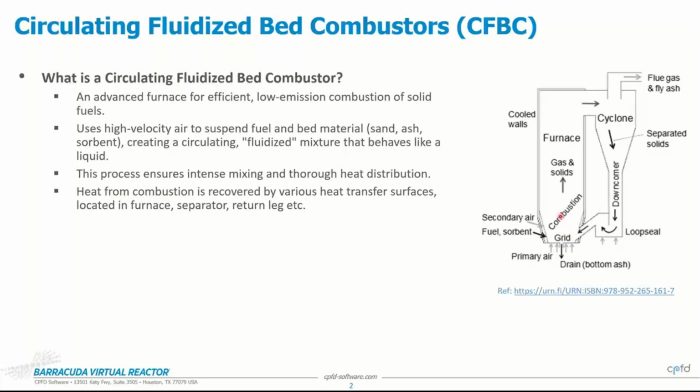And then as you move up this reactor or this riser section of the CFB, you have several secondary air injection points, right? And the idea is to do a staged combustion with that, and we'll come to that in a second when we go over some of the results here. But that's essentially the idea.